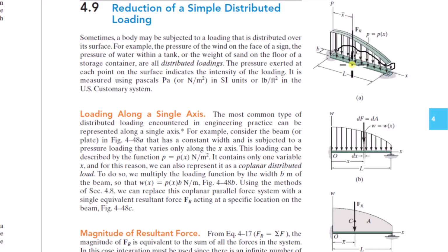So now all you need to do to get the force over that area is take a small dx and walk in the x direction, right? The idea is newtons per meter. If you're trying to find the actual load, not the pressure, you multiply newtons per square meter by the area. Well, for a planar problem, you can simplify that so the only thing you need to do is multiply it by a length to get the force. And that's what you're doing.